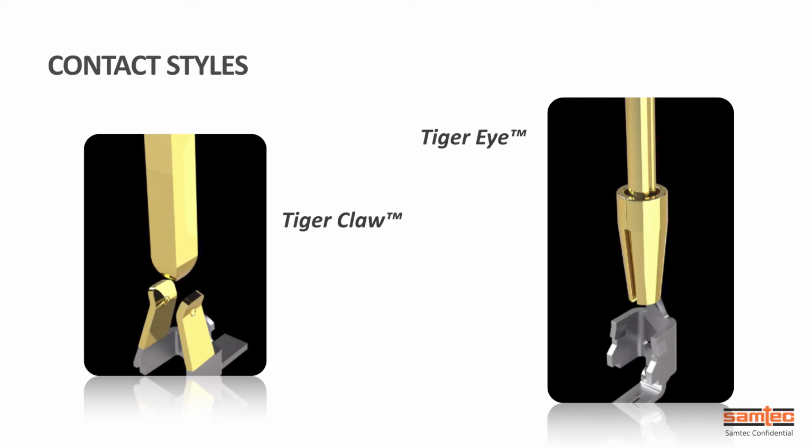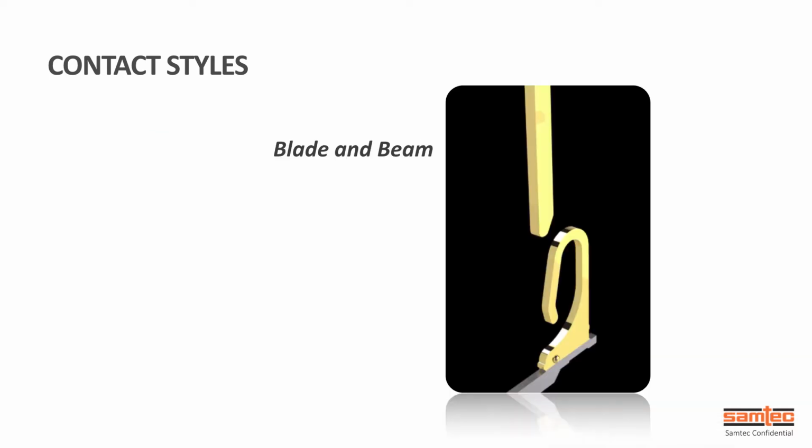But if you look at the features, there are many features that make those bends and beams come to play, which creates rapids and ripples in the signal condition through. So for high reliability, you may lose a little with signal integrity, not in all cases. If we go to a flat stamped contact, we can stack the pins very tightly within the plastic and make extreme micro-pitch contact systems.